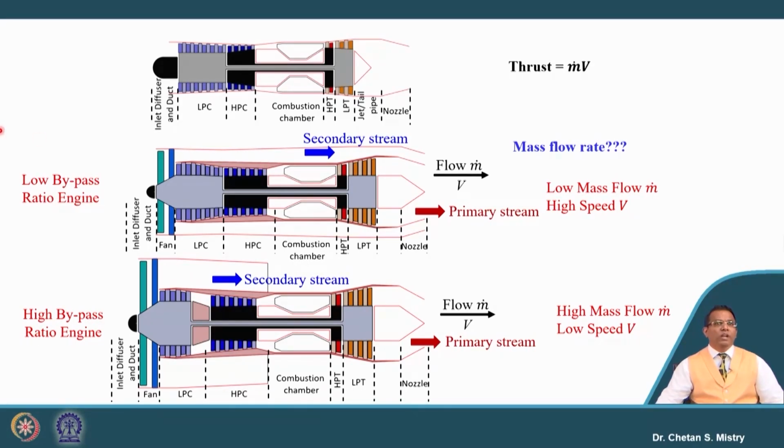Okay. So, now let us see what are the uses of this engine. Say low bypass ratio engine, since their dimensions are smaller, slightly higher compared to turbojet engine, can easily be fitted in military aircrafts, because we have a constraint with the space available to accommodate the engine. That is the reason why the low bypass ratio engine has major attraction towards military aircrafts. Even for business jets, people are looking for special kinds of application where we have low bypass ratio engines.